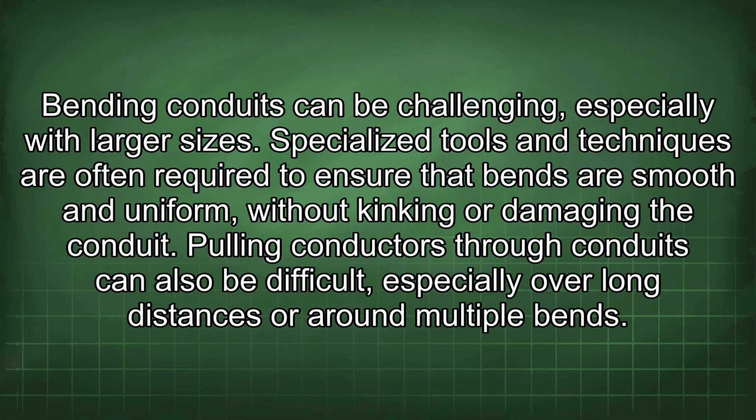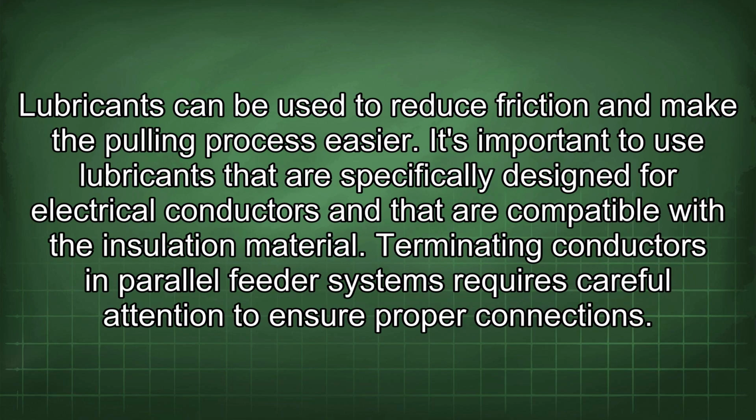conduit. Pulling conductors through conduits can also be difficult, especially over long distances or around multiple bends. Lubricants can be used to reduce friction and make the pulling process easier. It's important to use lubricants that are specifically designed for electrical conductors and that are compatible with the insulation material.